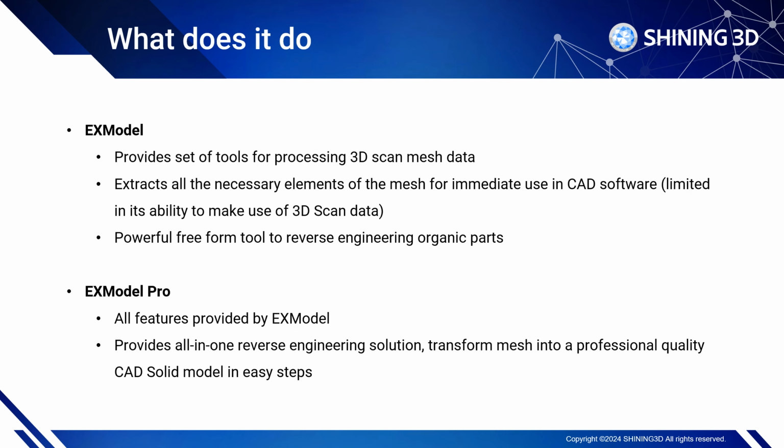It's possible to extract elements of the mesh so that you can output and use them in your own CAD software. You can do things like making a sketch or some basic features like planes, cylinders, then put them all into an IGS file and open that in your own CAD software, like SolidWorks or whatever, and do your modeling there later.